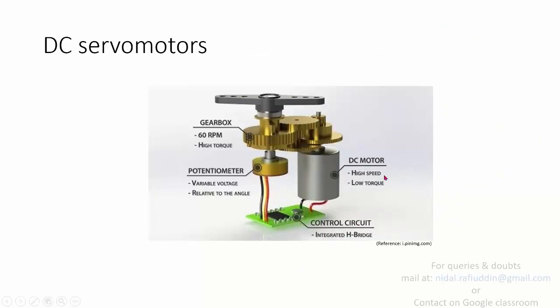I showed you this image, and in this particular image you can see that the DC motor has only two terminals. This shows that the motor shown here is a permanent magnet type motor. A separately excited motor should have four terminals: two for the armature and two for the field. In the case of an armature controlled DC motor, we obtain the feedback and send the voltage signal to the armature terminals while keeping the field constant.